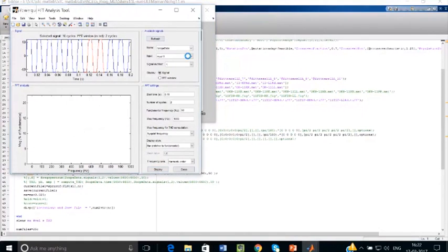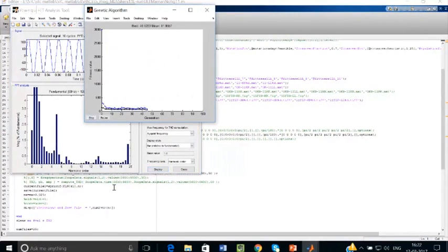So here I can just go and select my THD for the second line voltage and just display. Each and every time, each iteration, it will display the answer and those answers will also be saved there. So now I can see for which modulation index I am getting the minimum value.